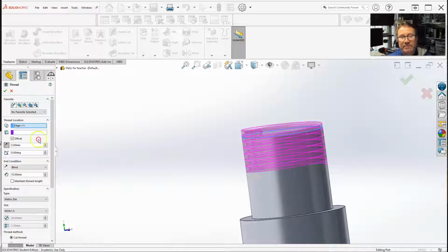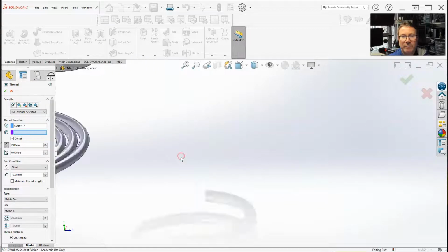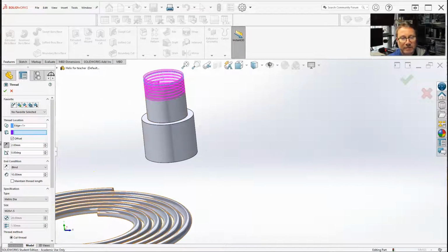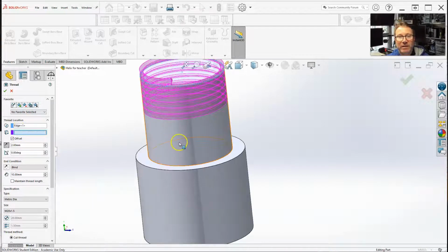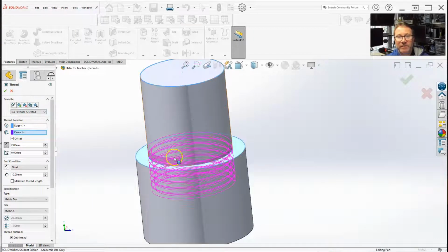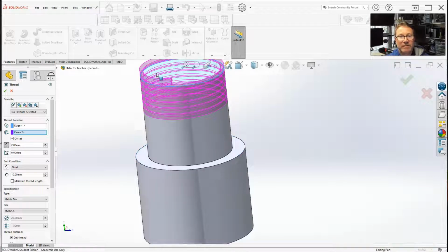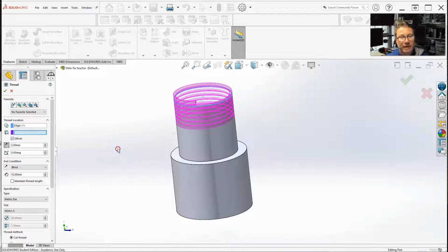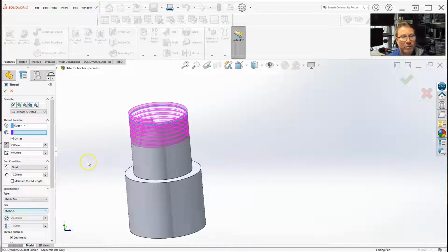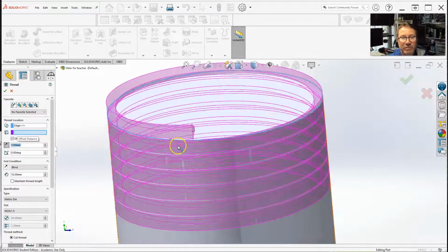Once again, our offset sets it up and down. I guess you could do a surface. And selecting a surface is, you got an edge, and then you can select a surface. That gives us our profile. If you want, you can always select, let's say I wanted to start down here, it'll just transfer it to where you want. I don't have to have offset, but I'll keep the offset for right now. Actually, since it's a 20, let's do a 20 1.5. So technically 1.5 should be enough to put it right above it.